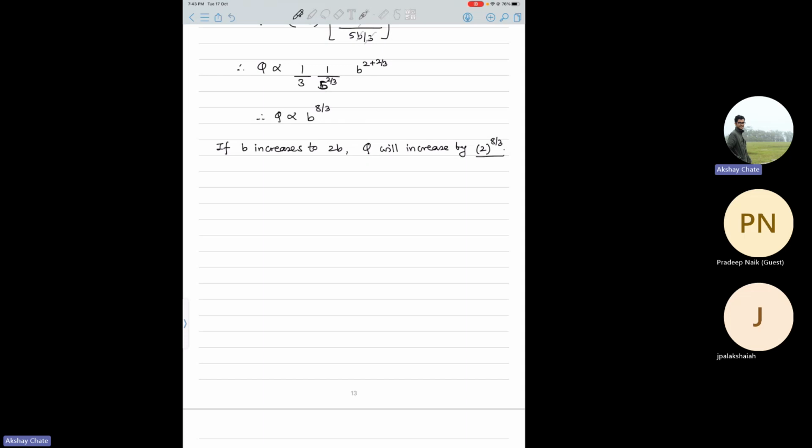So basically they want minimum pressure loss due to friction and maximum flow rate. Maximum flow rate will happen if you have maximum hydraulic depth for a given flow area, and minimum wetted perimeter will result in the minimum frictional loss. So there is no fixed formula.